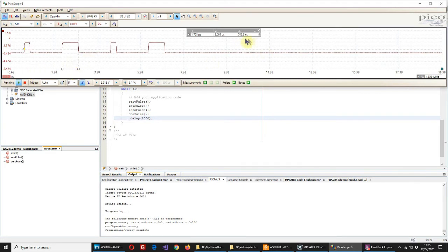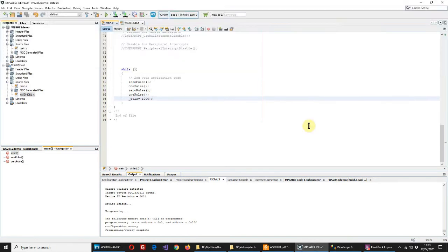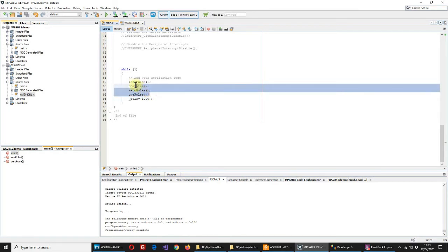This is our 1 pulse, which is 746 nanoseconds, which is within the spec, and then we just repeat it so that there's a low period following that, again about 1.5 microseconds, which is absolutely fine. Okay, so we're happy with that, our pulses are giving us the right timing. It's going to make the LEDs work.